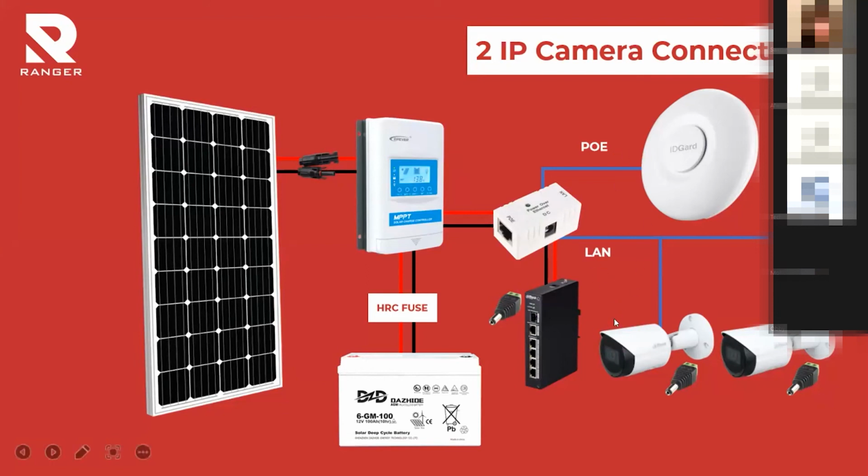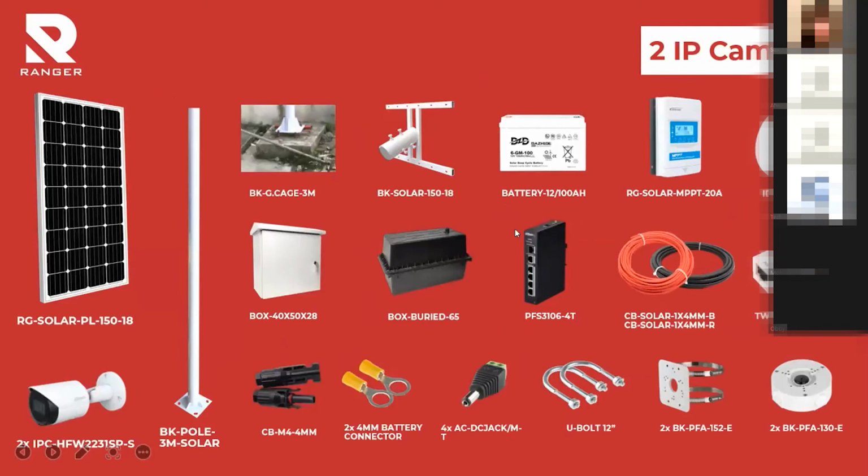Okay, so I just showed you this connection. The difference between 2IP and 1IP: for 2IP or more cameras, you need to add a network switch. If there are more than 4 cameras, you need to add an 8-port switch. Less than 4, you can use a 4-port switch. So the only difference in items is the network switch.